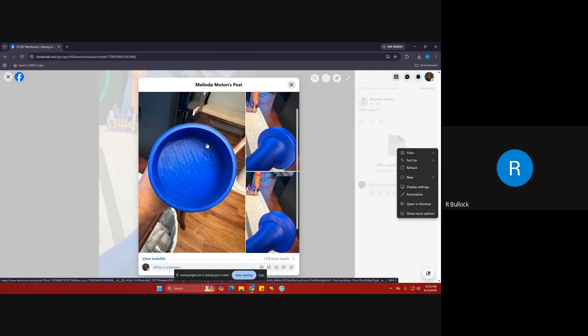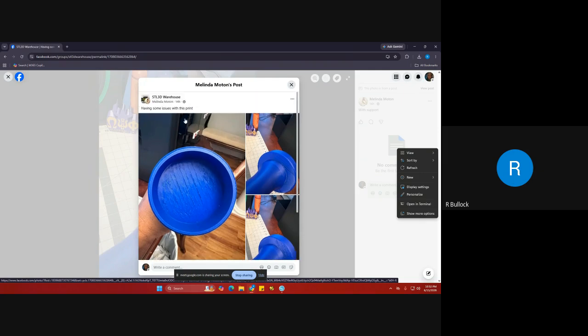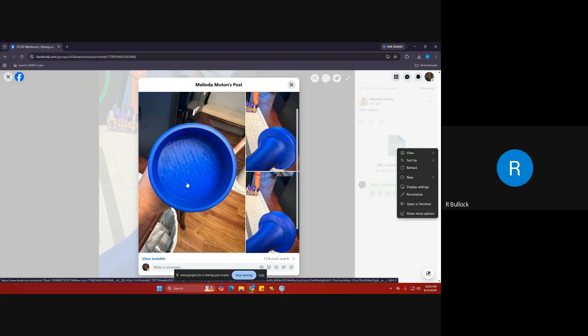So when I see stuff like this in a post, not saying this particular person in general, but when y'all get it in our inbox and you bring this to us, this is not a file issue. That is a printer and setting issue, guys, a filament issue. Maybe your filament's not dry. But I need y'all to stop thinking that it's automatically the file when you run into issues like this. Please.